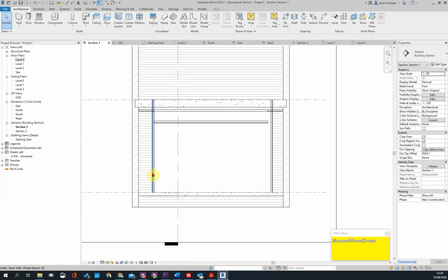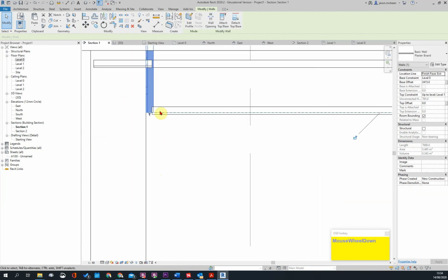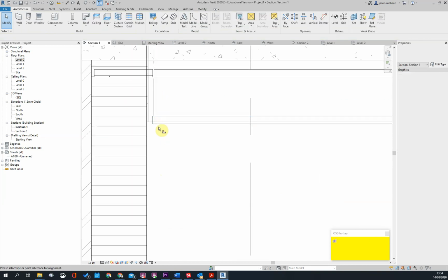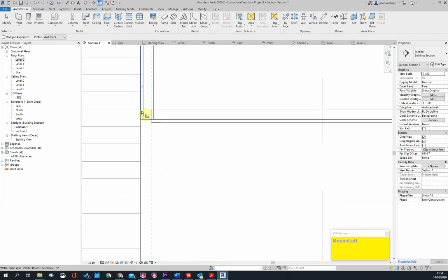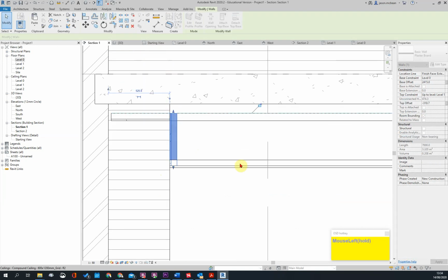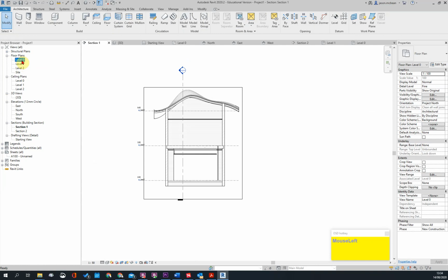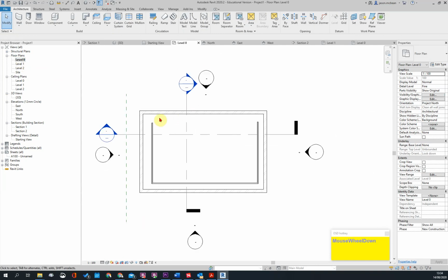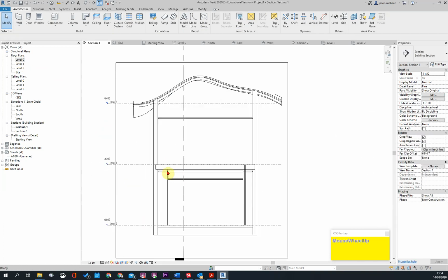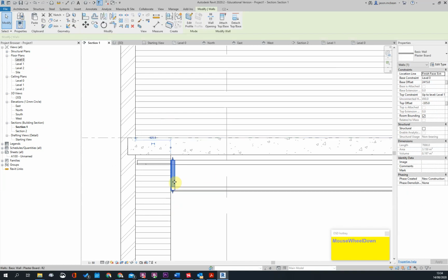Okay. So here's this wall, but this wall generally starts, okay, and it's going to align to there, and it will stop over there. So I'm going to grab this property. So all I can do now is I can go back to my level 0, and let's go to the section first. I'm going to use the match tool. I'm going to select all of, use match tool, MA. So select this wall here.